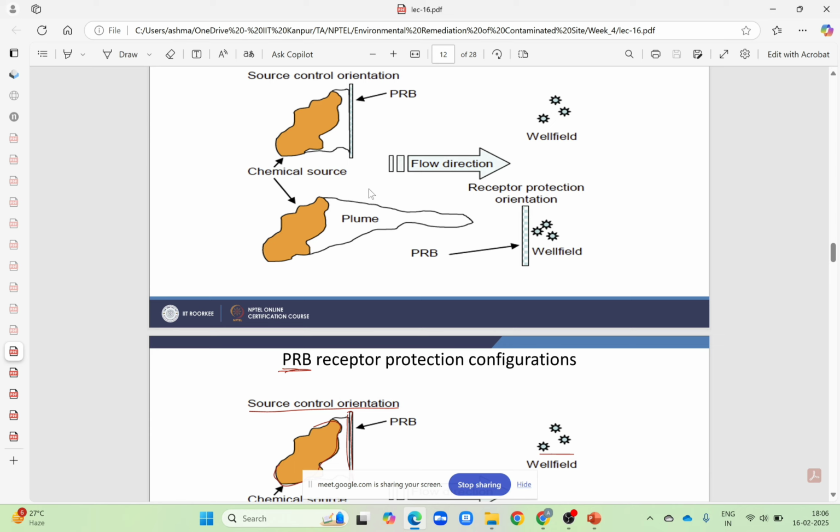Basically the contaminant is sorbed on the solid sediments or soil in the aquifer, and it gets dissolved in the aqueous phase when the concentration is reduced. And also we have seen that when there is some NAPL, that is the non-aqueous phase liquid, then the retardation factor is very high, and the remediation time for the pump and treat method is in years. Sometimes it comes out to be hundreds of years.